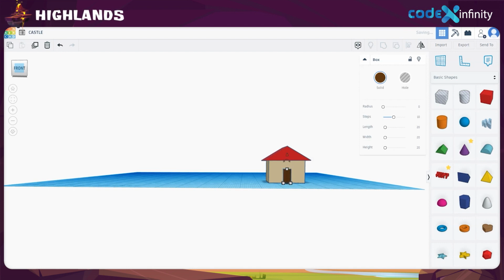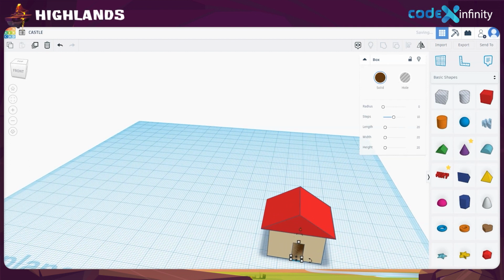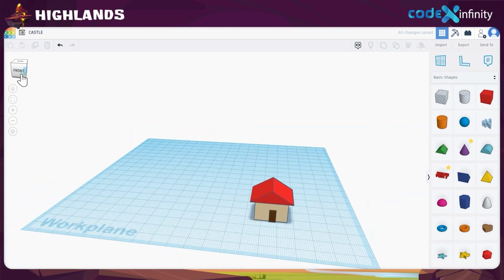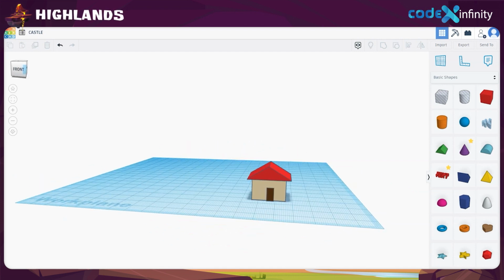That's it. Now place it at the exact center part of the bottom of the front position of the wall structure using the arrow keys. Now, to have a more clear view of the position, let's adjust the 3D cursor to get a view from the top of the gatehouse. Just zoom into the door's position and make the appropriate adjustments required using the arrow keys. Alright. Now, let's have a thorough view of the alignment of the door from all the directions using the 3D cursor. Well, don't you sense a little fault with the alignment of the door? It's not exactly at the center position, right?